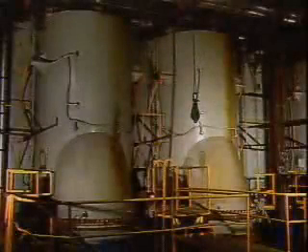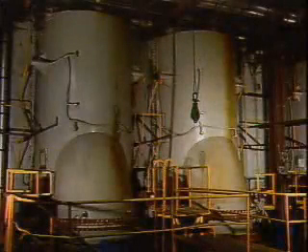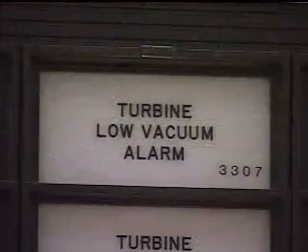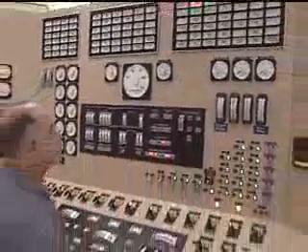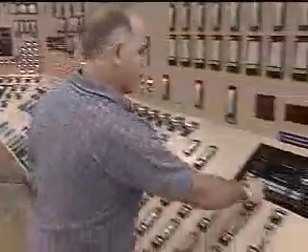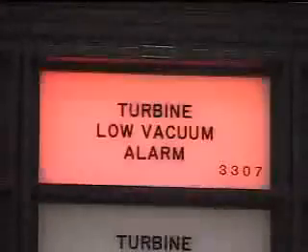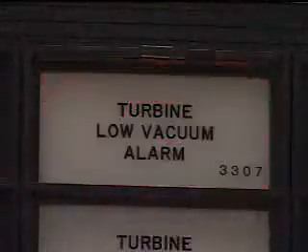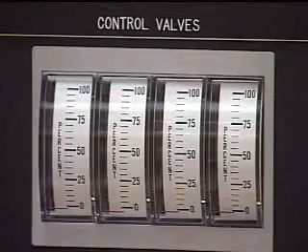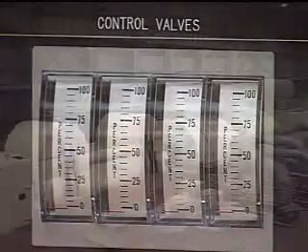Two safeguards that protect condensers and turbines from damage caused by high internal pressure are low vacuum trips and rupture discs. A low vacuum trip is connected to the turbine control system. Several alarms are generally received before a trip. This allows power to be reduced and the required actions to be taken to prevent a trip when the loss of vacuum occurs gradually. In any case, if vacuum drops below a certain set point, the low vacuum trip operates automatically to trip all of the turbine steam valves closed. This stops the flow of steam to the turbine and protects the turbine and the condenser from overpressurization.